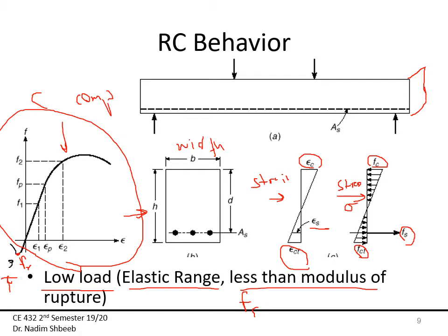There are no cracks developed because I'm not going over the strength in tension for concrete. And at the same time, because again, the compression, I'm still operating somewhere over here. Okay, so again, there's no failure over here as well. So this is showing me, again, there's no cracks developed. I'm at low load, still at the elastic range, as we say. The stresses are less than the rupture strength of concrete in tension.